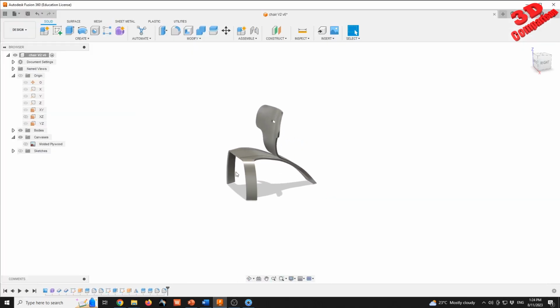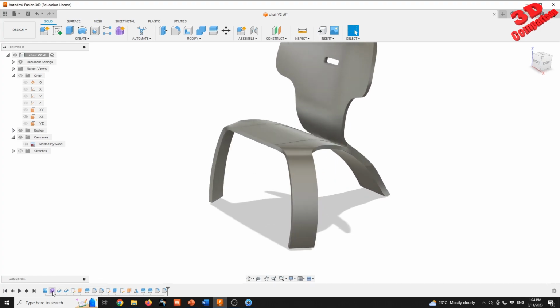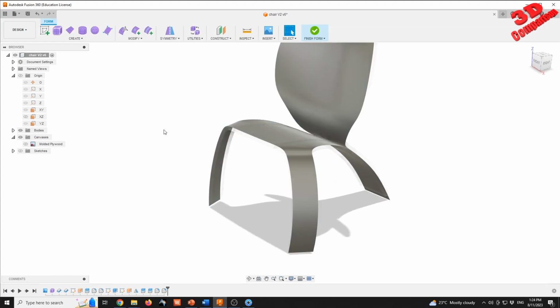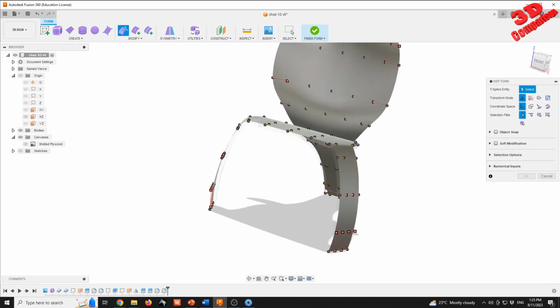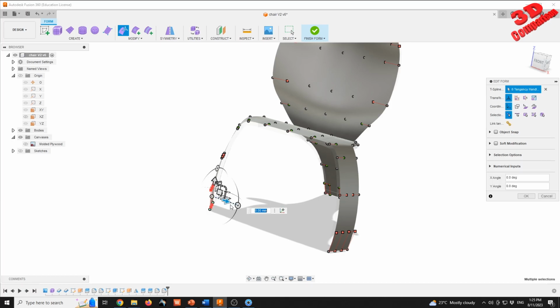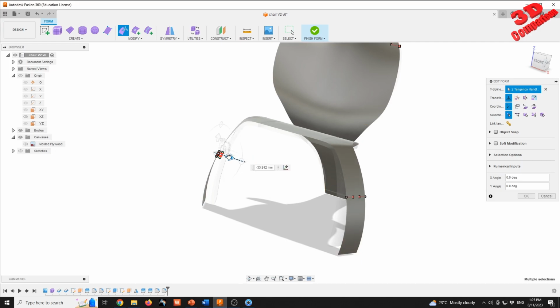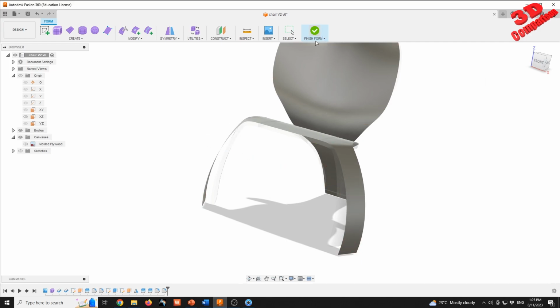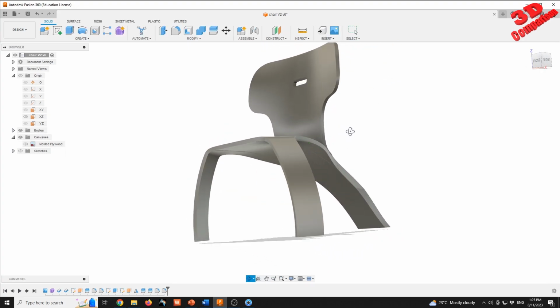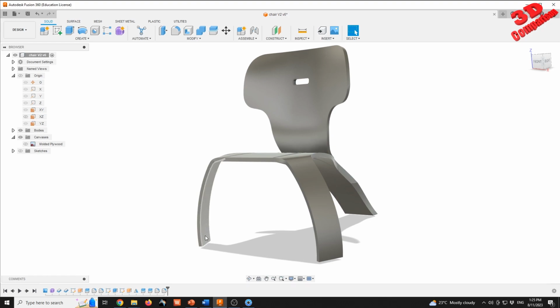We can easily change that within Fusion. I'm also gonna make a separate video just regarding this step within Fusion. So since we have mirror over here, I can just select those points and have them moved. The only side effect of this is that when I will click finish form, Fusion will need time in order to process all of those. So we see computing thicken because I added that 18mm for the plywood. But now it managed to do that. And now that curvature will be, let's say, better. And I can also slightly adjust over here at the top as well.